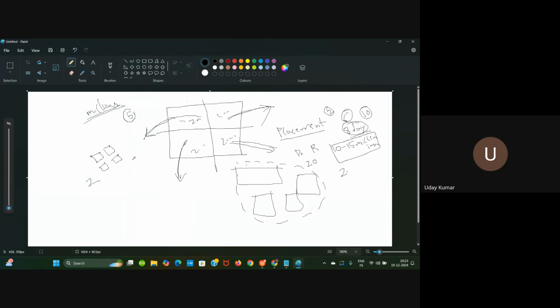Then you need to merge everything and go for a flat. This flat will have some glue logic, and the top level guy will take as inputs the block level Verilog, block level spec, and block level defs, which are also called ILMs.